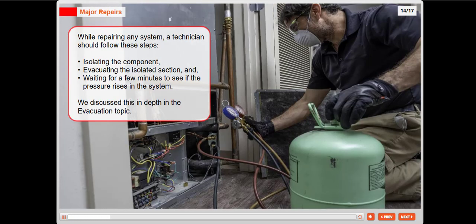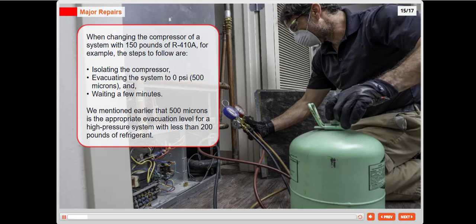While repairing any system, a technician should follow these steps: isolating the component, evacuating the isolated section, and waiting for a few minutes to see if the pressure rises in the system. We discussed this in depth in the evacuation topic. When changing the compressor of a system with 150 pounds of R410A, for example, the steps to follow are isolating the compressor, evacuating the system to 0 pounds per square inch, 500 microns, and waiting a few minutes. We mentioned earlier that 500 microns is the appropriate evacuation level for a high-pressure system with less than 200 pounds of refrigerant.